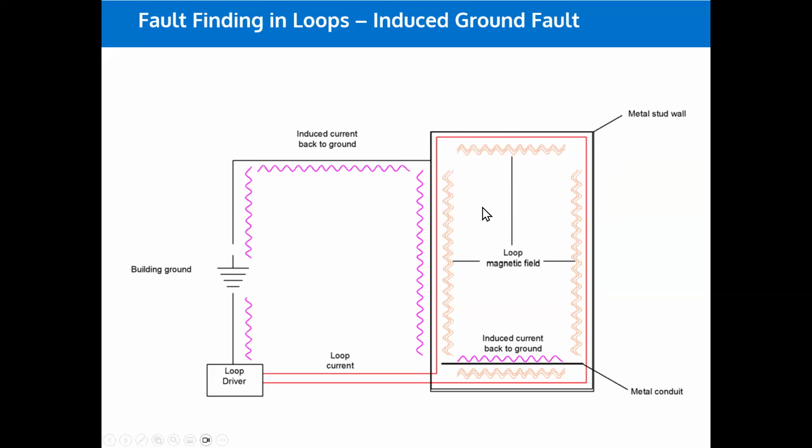Phased array systems tend to use lower current values, and therefore they don't induce as much current in any surrounding infrastructure. But it's certainly something that's a bit erroneous. There are no hard and fast rules as to why it happens and what can make it happen, and it can, as a result, sometimes be a bit of a nightmare to locate.